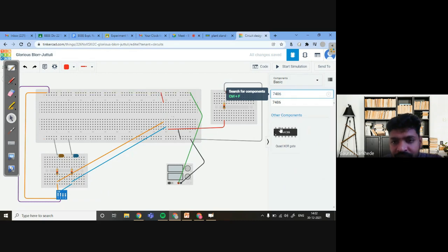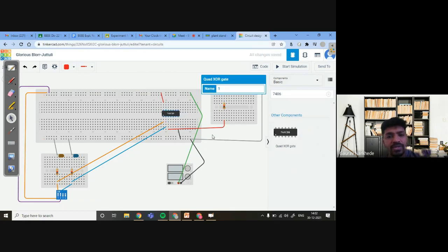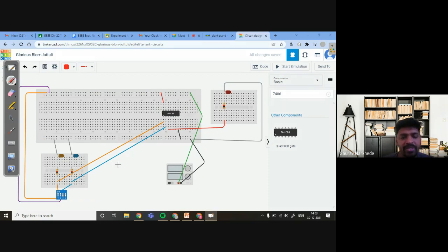And I am taking this IC and connecting it properly, right? So that this pin is your, correct. So see, this is input 1, input 2 and this is your output. Now see which table we will verify. This is A, this is B. For 0 0, output will be 0. If it is 1 0, output is 1; 0 1, output is 1; and 1 1, output is 0. So let me check this thing.